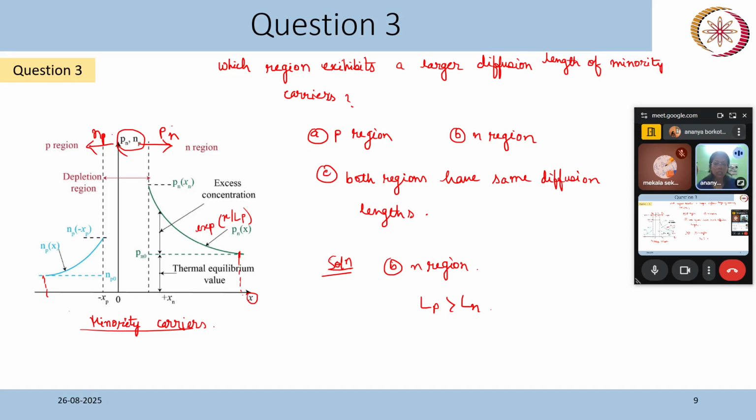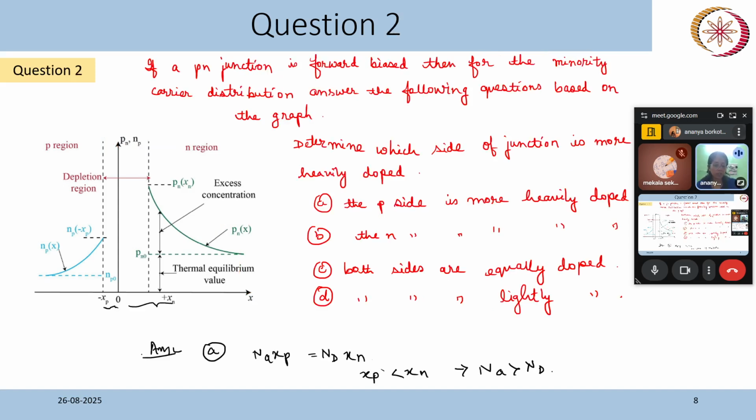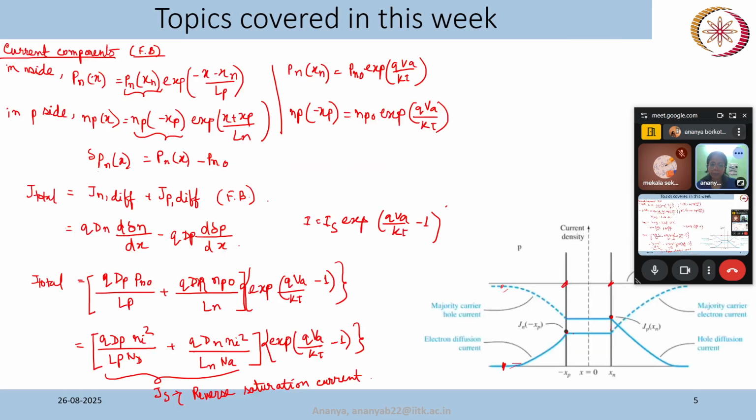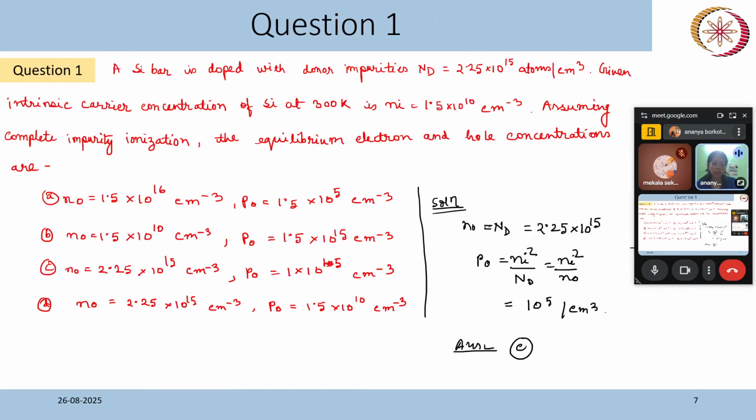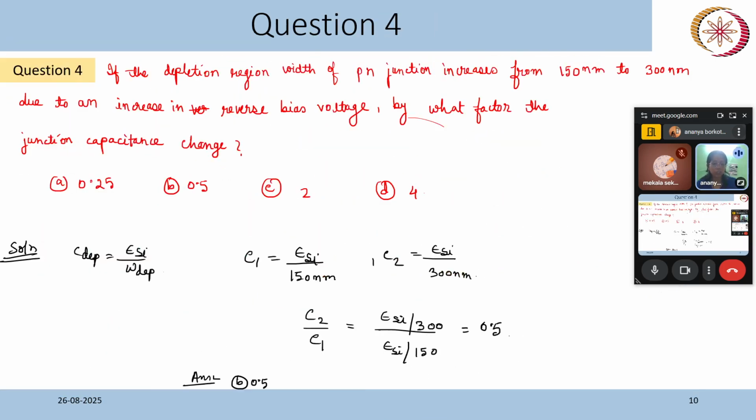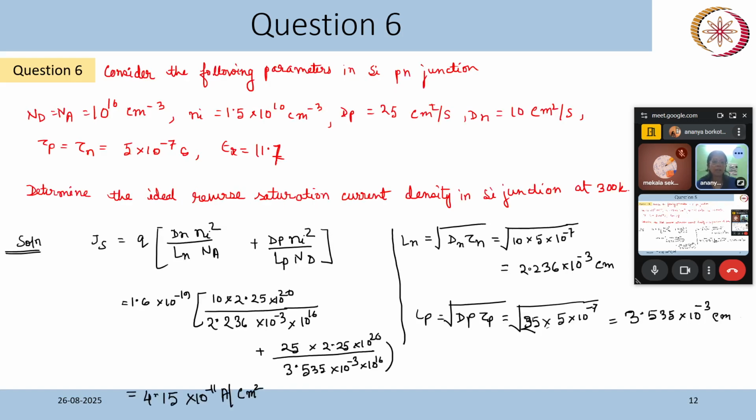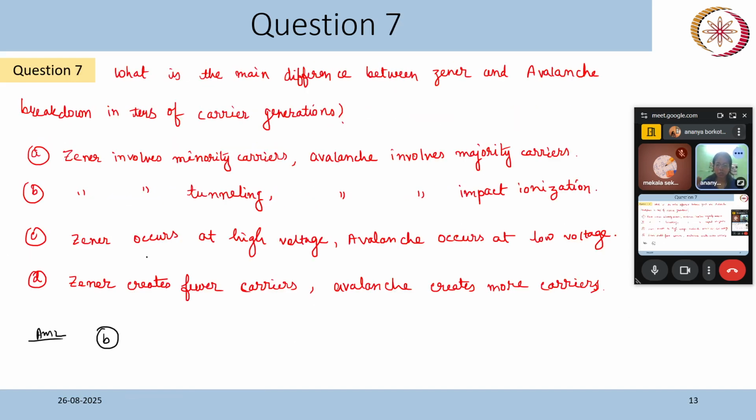And how will it change? See how the charge dq changes with respect to dV, exponentially, right? Where we are changing this VA by some factor. If we change it linearly, we actually get an exponential increase of the injected carriers, exponential increase of the charge. Okay, so diffusion capacitance changes exponentially with respect to the applied bias voltage. Okay, so the correct answer is this one.